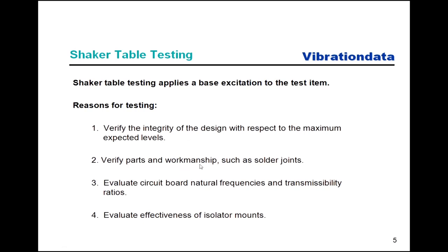Sometimes there's what are called lot acceptance tests. Let's say, for example, you have some explosive devices, pyrotechnic devices to go on a rocket vehicle. Well, you want to subject it to vibration, but then if you want to see if it still works after vibration, you have to set the explosive device off. You have to detonate it. Well, when that happens, it can no longer be used because you've just used it up.